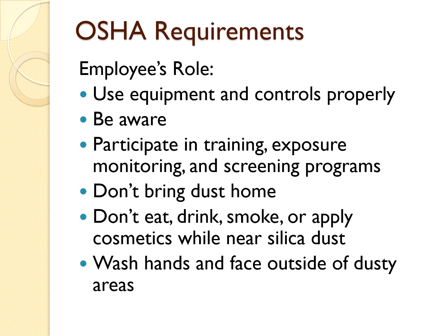OSHA requirements continued. Employees' role: use equipment and controls properly. Be aware. Participate in training, exposure monitoring, and screening programs. Don't bring dust home. Don't eat, drink, smoke, or apply cosmetics while near silica dust. Wash hands and face outside of dusty areas.